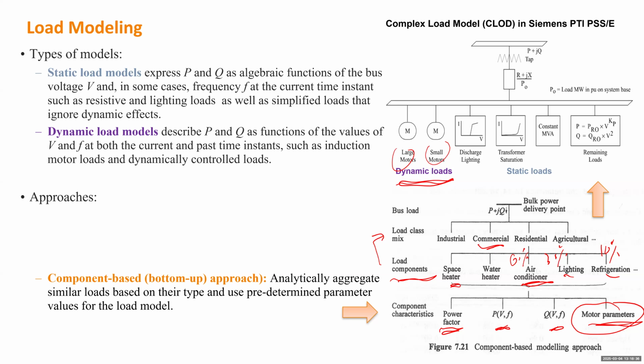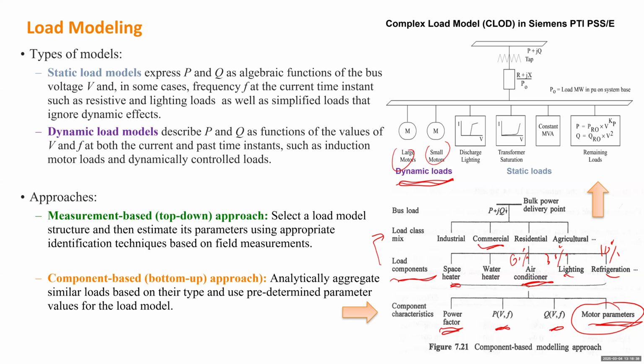So that will bring this second approach, which is a measurement-based approach. The measurement-based approach is if you already select a load structure, which involves a number of parameters, you need to collect the measurement data and identify those parameters, to validate each parameter. You may take an optimization approach by allowing the parameters in the load model to vary a little bit and see which one can fit the measurement data the best. So that will be the final load model.